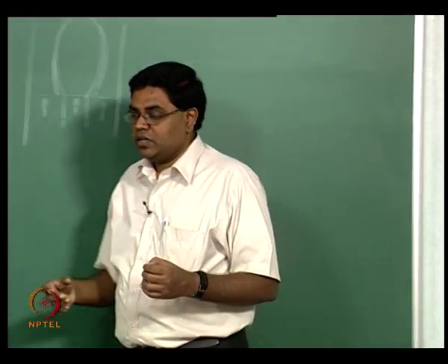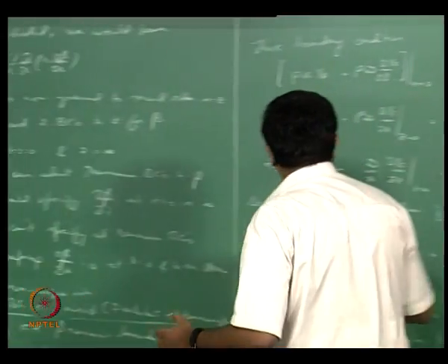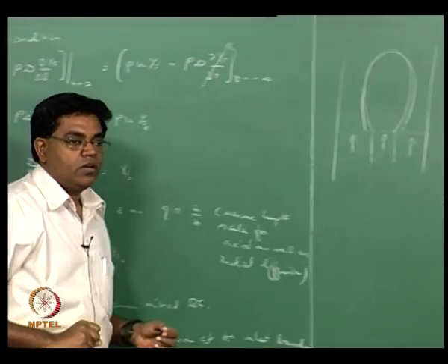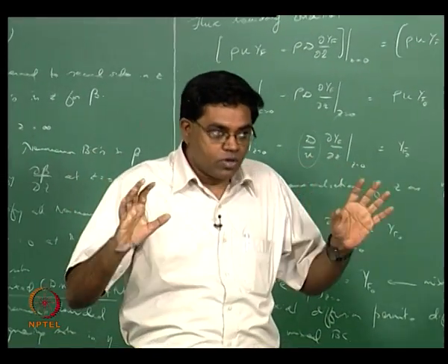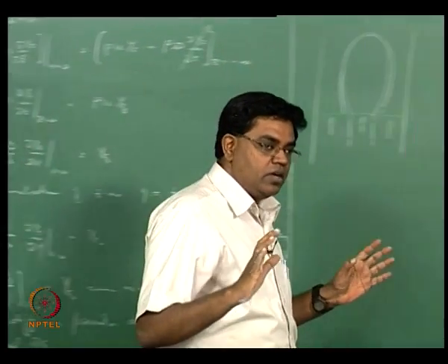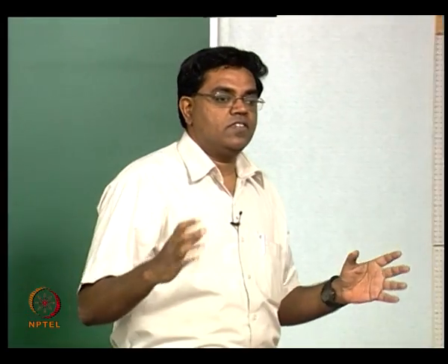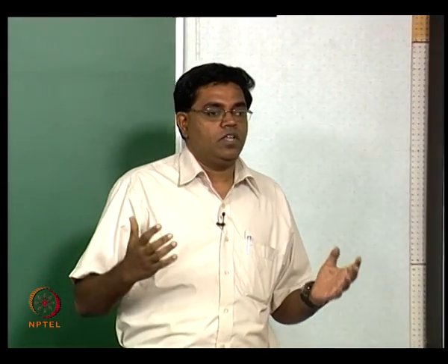So on the one hand the Burke-Schumann problem would actually mean this problem. A Burke-Schumann flame in the literature now comes to mean any stoichiometric surface that is now coincident with a Burke-Schumann flame. That's essentially what it means. That means we are adopting the infinite rate chemistry assumption, or the flame sheet assumption, or the mixed-is-burnt approach, or whatever it is. You can call it in any other way. Anyway, this is what we are talking about.